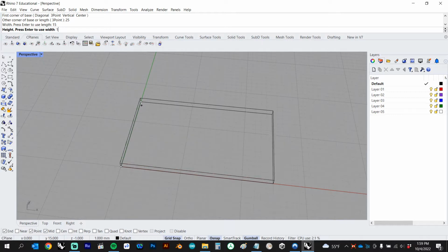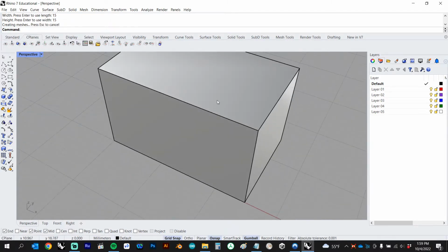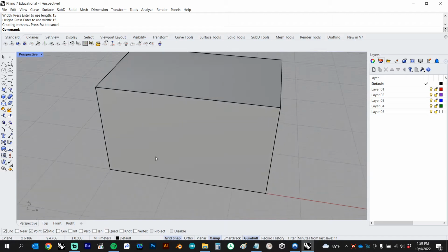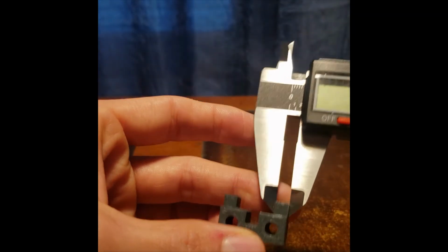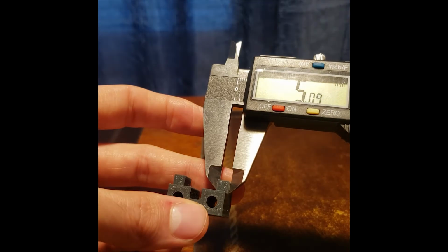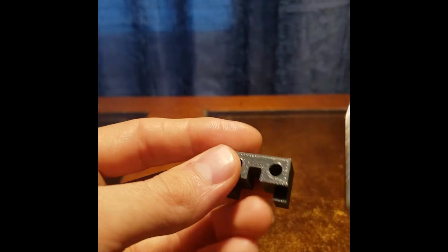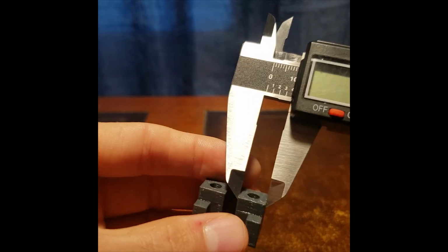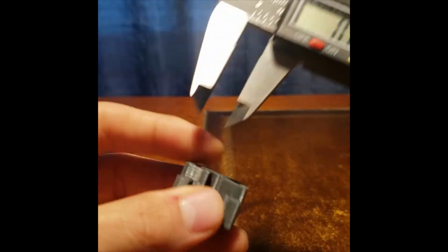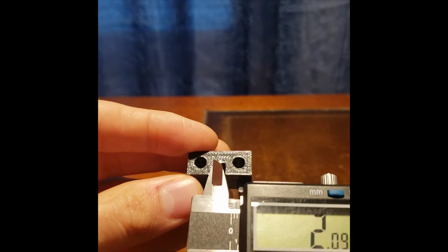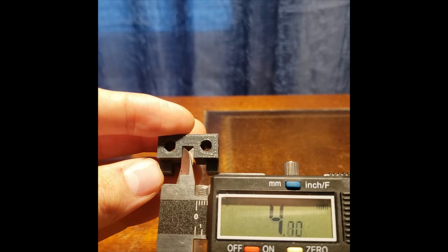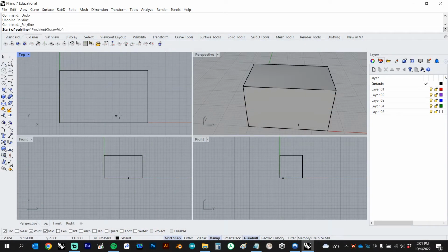Now we need to think about the shape of the geometry we need to create that we can use as a cutting object to remove material from this primitive. By viewing our shape from the top down, we can get a better idea of the type of curve we need to create that we can extrude into a solid and then use to subtract from our cube. I'm going to measure all of these edges just to get a value for each of those distances. For this part of the cutout, you have to use your internal measurement probes on the other side of your calipers.